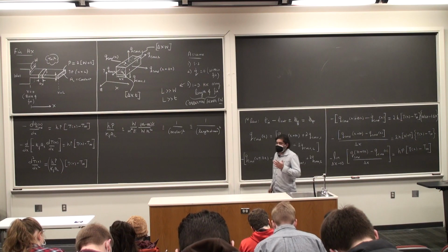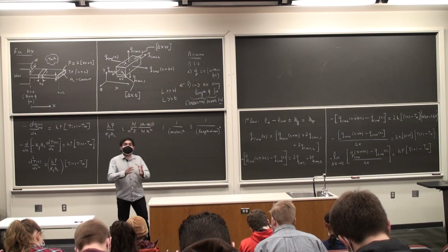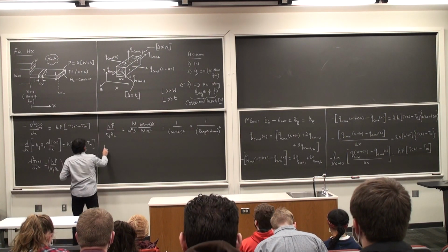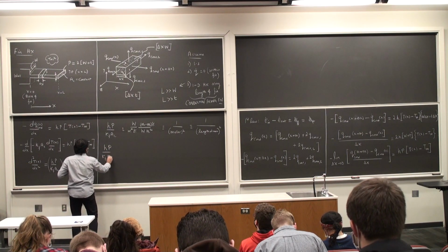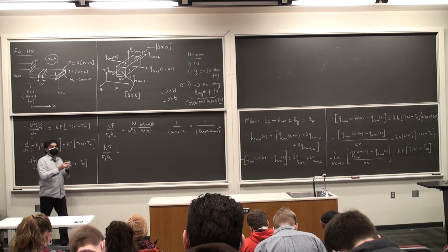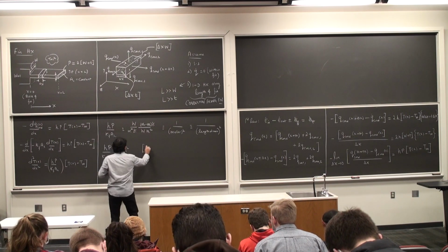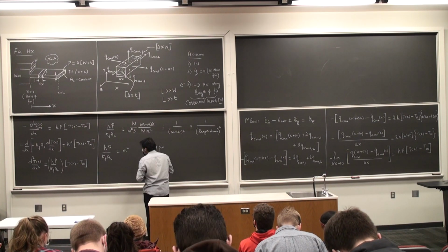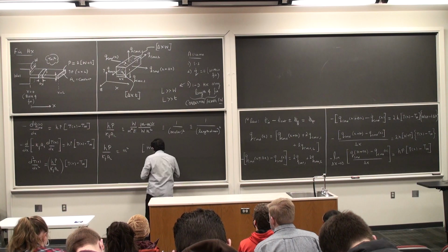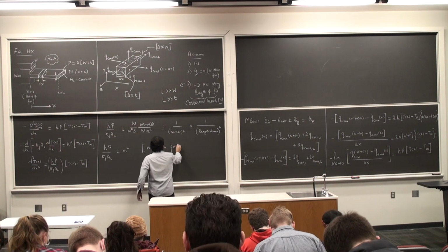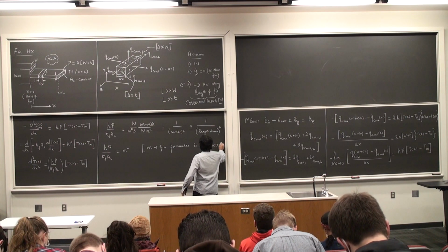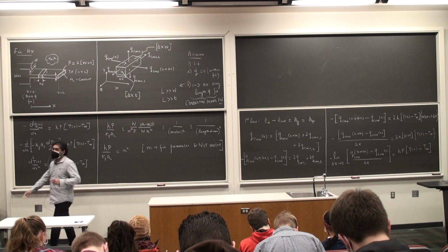This quantity has a name, does not have a name per se, but it is denoted by the symbol little m square. Okay, so this entire quantity here, hP by k_f A_c, is going to be called from now on as m square, not to be confused with meter square. Okay, so this is m square. m is a fin parameter. I always say fin and pin, they're pretty much the same. You have pin fins, which makes it even nicer. Its unit is per meter. Okay, please make a note of this.